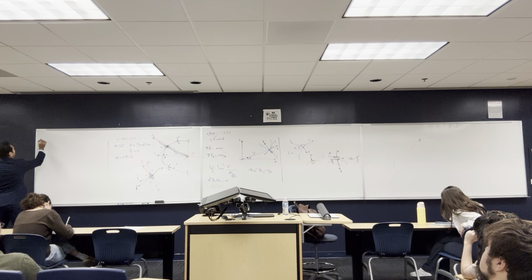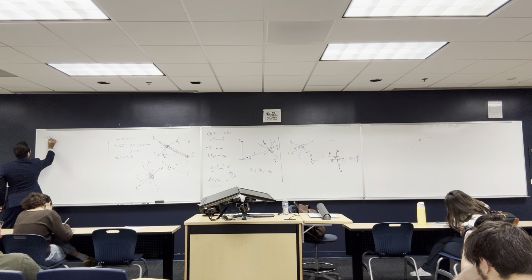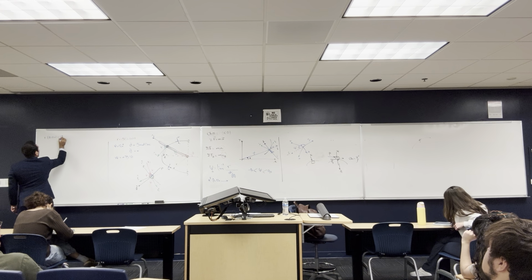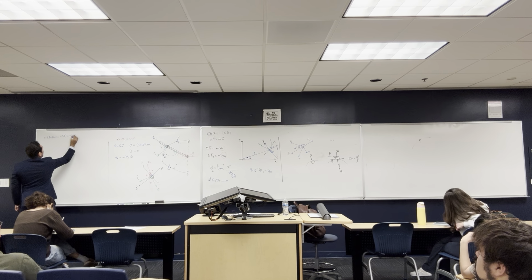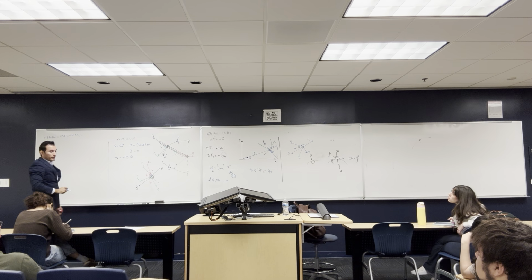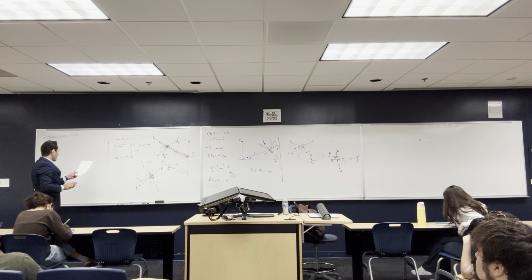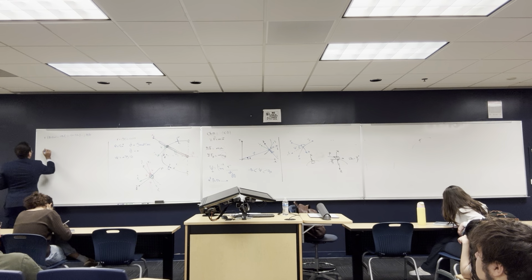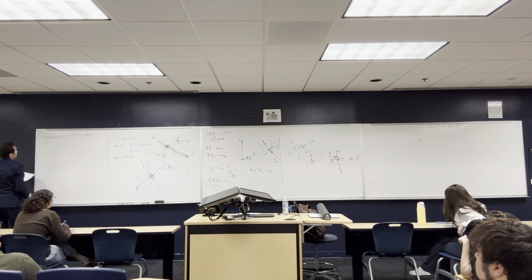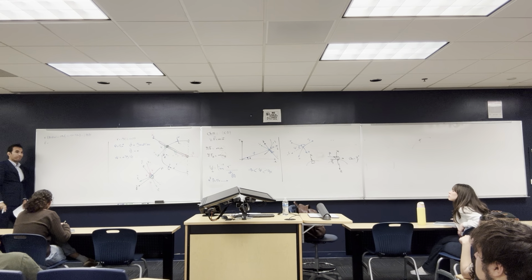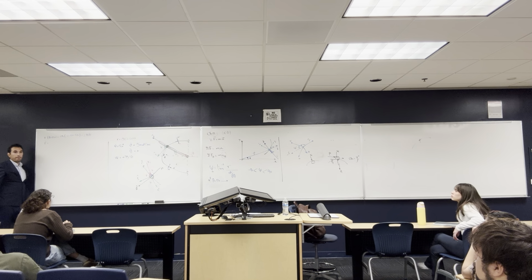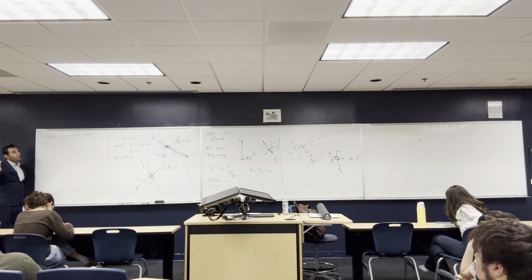So, first I have R at theta equal 120 degrees, gonna be equal to 1.5 times (2 minus cosine 120 degrees). And this is gonna give me 3.75 foot. And I need to get R dot. R dot, you guys tell me, how can I get R dot? I have to differentiate with respect to the time. Can you differentiate this with respect to the time? Tell me. I'm gonna write.